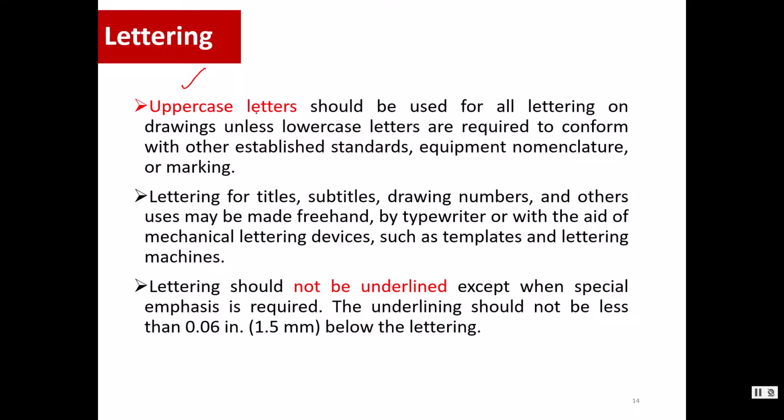So most of the time, uppercase letters should be used for all lettering on drawings, unless lowercase letters are required to conform with other established standards, equipment, or markings. So most of the time we just use uppercase letters, but it also depends on whether the standard requires lowercase, then we can also do that. Lettering for titles, subtitles, drawing numbers, or other uses may be made freehand or by typewriter or mechanical lettering devices such as a template or lettering machine. So this is for the manual drawing.